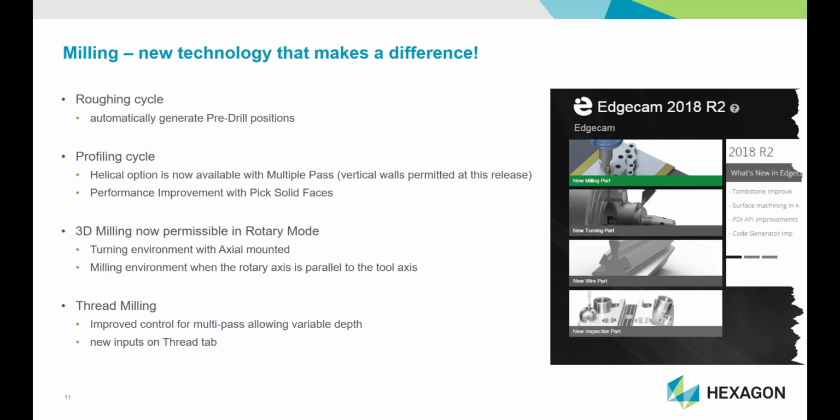So if you consider your standard turning center that has turret-based live tooling, C-axis, and let's say it also has a Y-axis. The Y-axis has a limit of travel, usually about plus or minus 2 inches on a modern machine, and the X-axis also has a limit of travel. If I have a face-mounted tool, the tool can operate past the center line for only a short distance. It really has to stay mostly on X positive. So if we have a larger workpiece, we need to constantly move the rotary axis to keep the part in the zone where the tool can work.